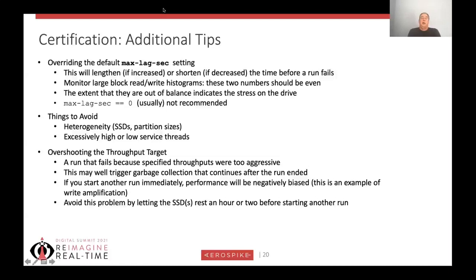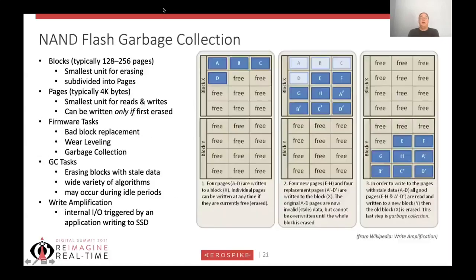So if you started another run immediately, that's going to hurt your performance. This is an example of write amplification. And so the best advice is let it rest an hour or two before starting another run.